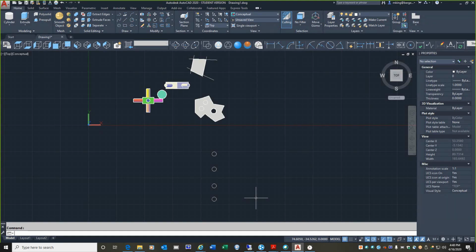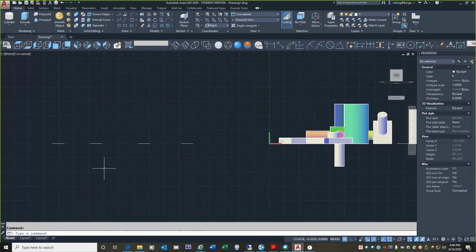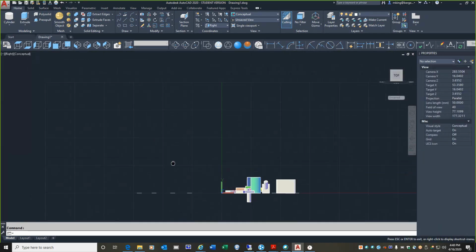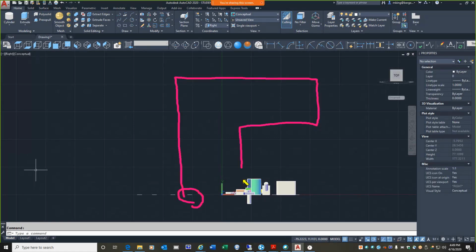All right, now what I want you to do is select right side view right here. So we're going to look at this from the right. And those circles look like lines, right? Little pieces of lines, because we're looking at this in edge view. So zoom out like I have, so I'm pretty far away, and I'm panning downward, because I want to do something with this circle where I have a lot of space in this area, above and to the right.